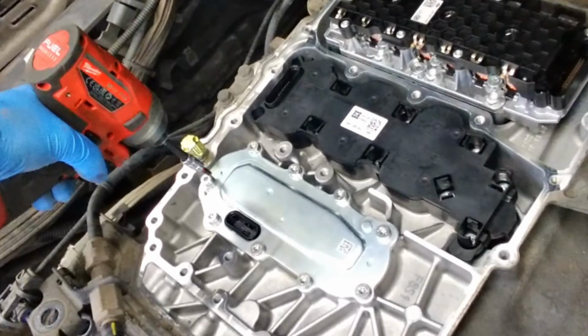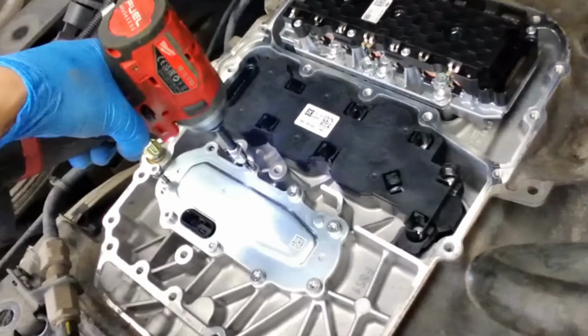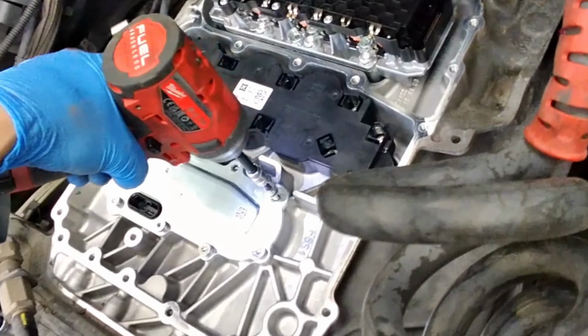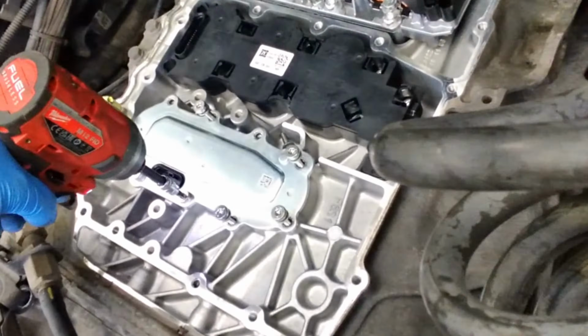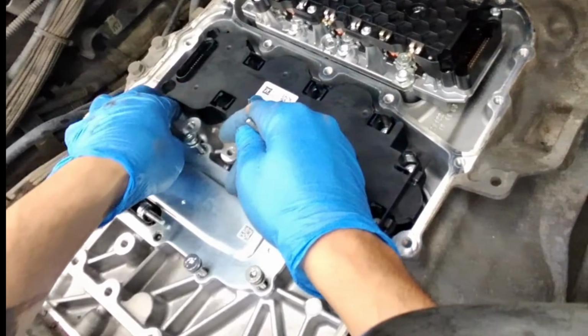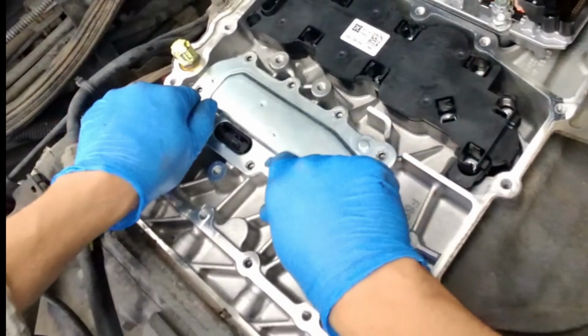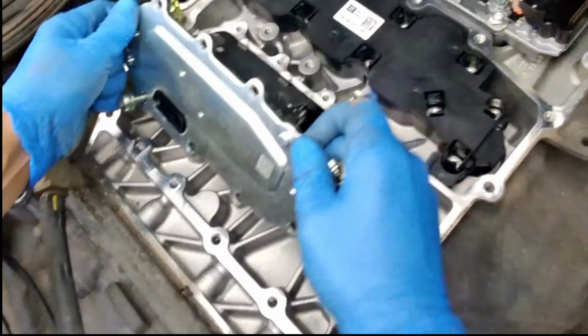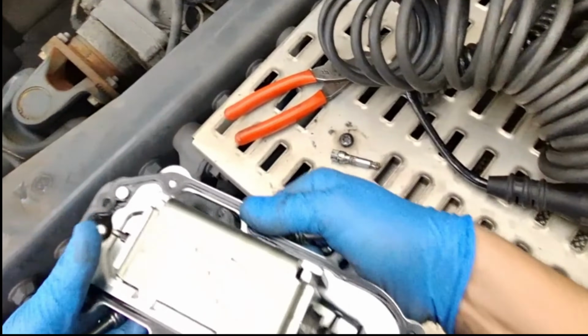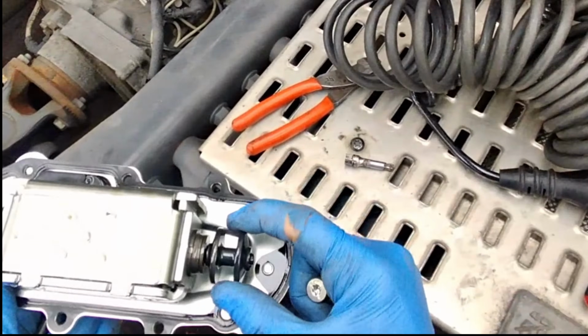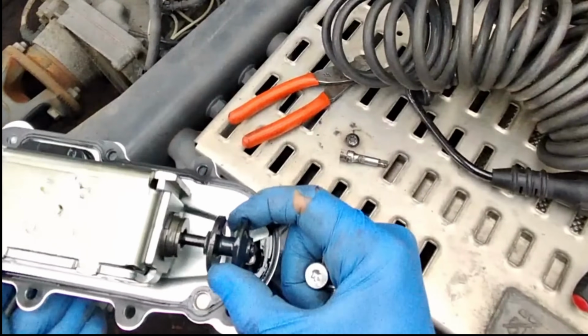A 12-speed transmission uses two main gear shift forks, and therefore two gate selection positions. The position is determined by the detection of the differential inductivity in the mechanical movement of the gearbox gate selector. This is done in the electromagnetic gate selector actuator, which is connected to the shift fork on the shift rail of the main transmission.